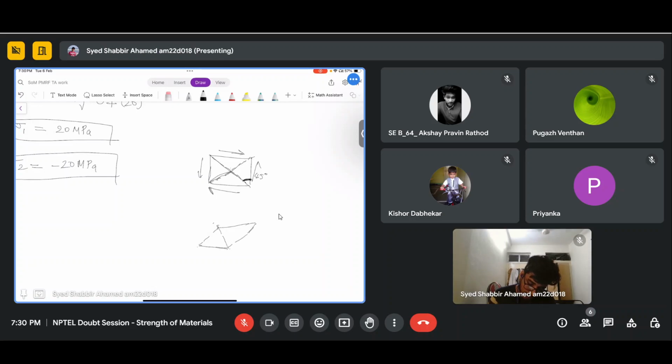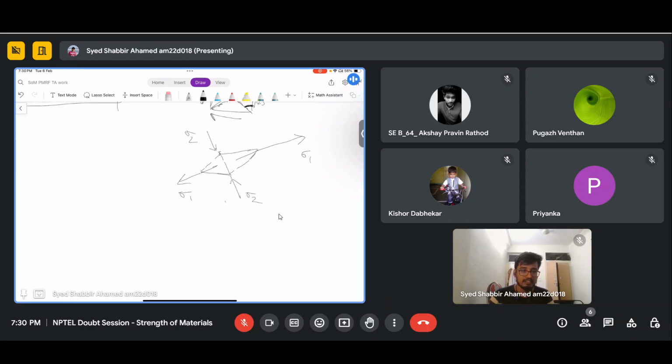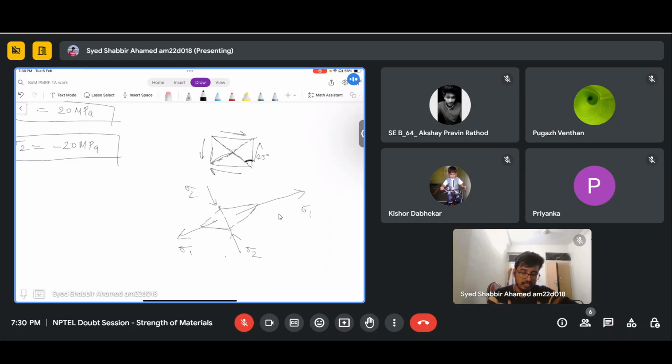So it will deform it. Here, due to this squishing, this is the normal stress acting. And here, this is compressing it, and that's why we have sigma 2 negative. I hope you can visualize this. This is dragging this like this, and in this direction it is getting compressed. Here it is getting pulled, and here it is getting compressed.